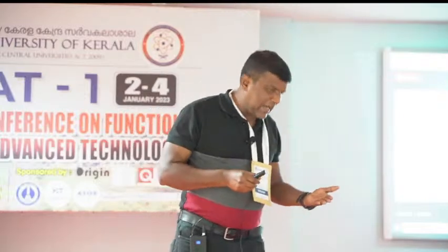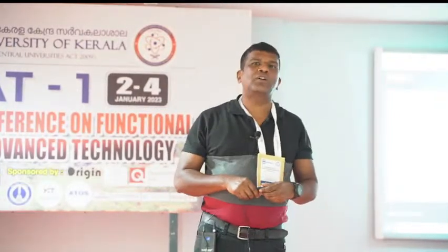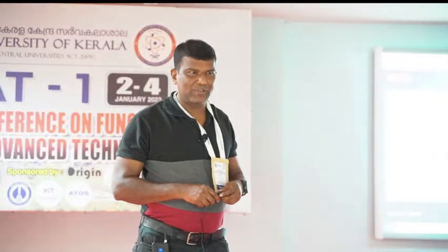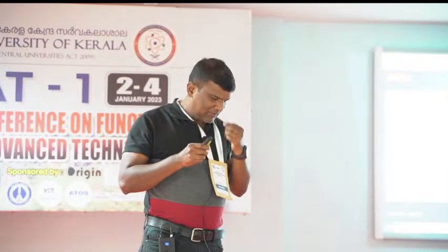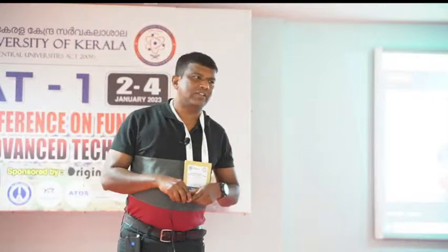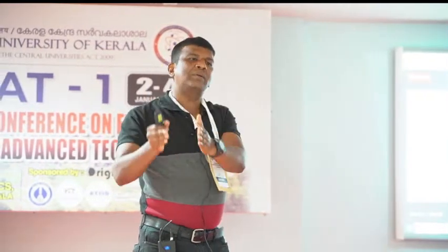So in that case, either your sample needs higher voltage, but there are also other constraints when using PFM signal. Let's say some samples do not like high voltage. If you apply high voltage, the sample breaks down. So in that way, as I probably already gave you some information, there is something called the dual actuation resonance frequency method. In that method, all these PFM signals that we are performing are away from the resonance.